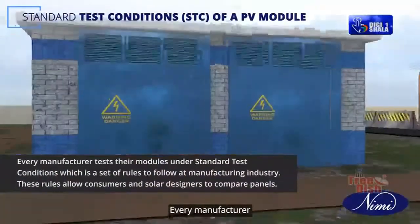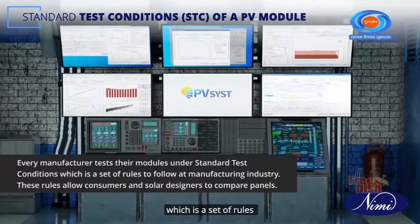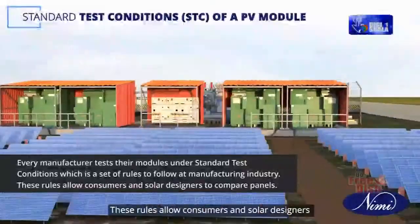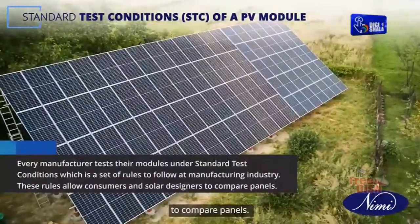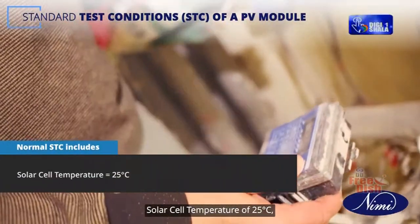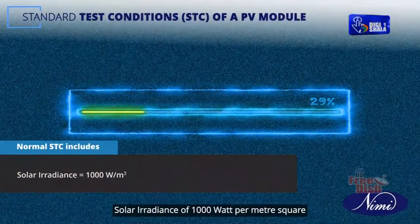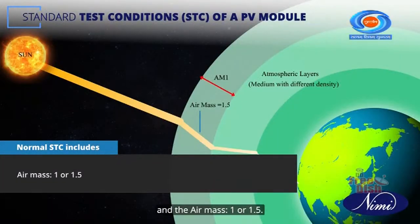Every manufacturer tests their modules under standard test conditions, which is a set of rules to follow in the manufacturing industry. These rules allow consumers and solar designers to compare panels. Normal STC includes a solar cell temperature of 25 degrees Celsius, solar irradiance of 1000 watts per square meter, and an air mass of 1 or 1.5.